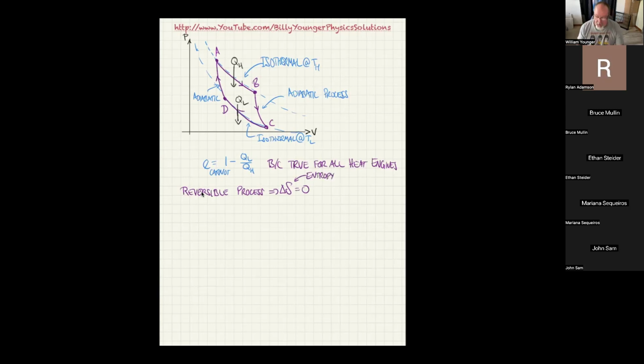So that's sort of the beauty of the reversible process, and the reversibleness of it. That is where the non-friction comes in. Because if you had friction, it wouldn't be reversible, because you'd go from an equilibrium state an infinitesimal distance to another equilibrium state. If that infinitesimal distance was across a frictionful process, then you'd lose some energy. So if you tried to go back, you'd actually go back to a different state.